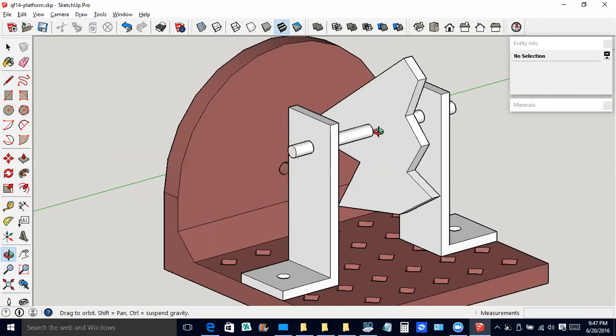And we'll need to have this thing so that it kind of holds its place. So we'll be putting a nut here and a washer, and we'll tighten, and probably over here too. And we'll tighten those things up so that we can still move this thing, but so that it won't slip back down when we take our fingers off.